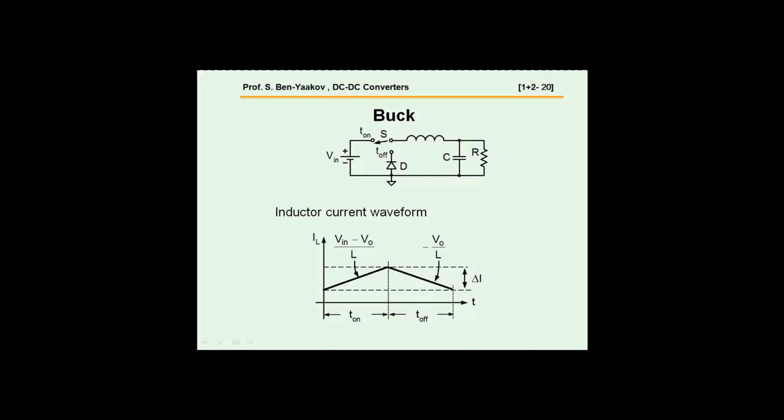As we understand then, we have, you might say, a toggle switch here, which connects the inductor to the input and then automatically to the diode. In fact, one can replace the diode by another transistor, that is, use two transistors like this.